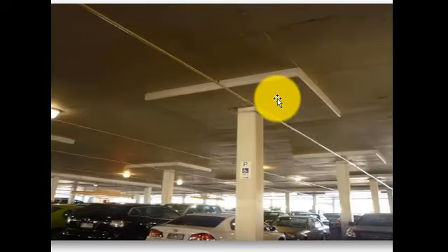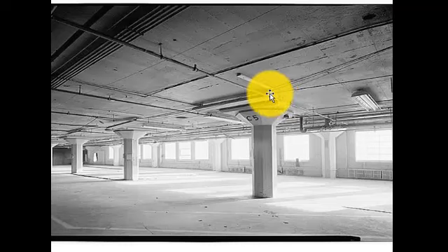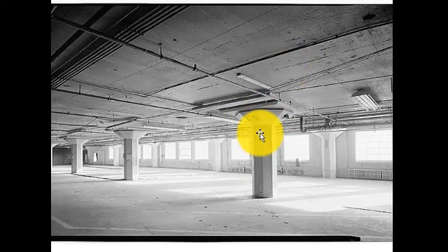So let's see the second one, which is the column capital. You see, you don't just connect your column directly to your slab. So here, this is a column capital flat slab. Look at it here. This is your column. It is coming uniformly. Then at this point, it increases. You can see it increases. So it is your column that actually increases here, not your slab. So that's why we say this is a column capital. It is your column that has a capital. Or you say it is a column head. It is your column that has a head.